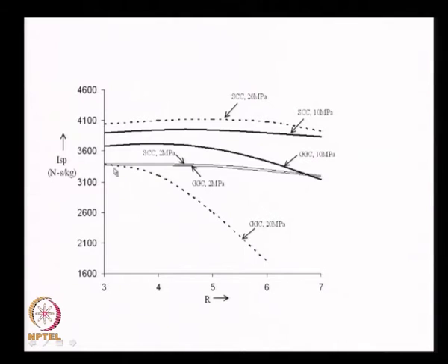All I am saying is, if I operate a gas generator cycle at a small value of pressure, this is the net value of specific impulse I get. If I operate the same engine on a stage combustion cycle at low pressure, I get a slightly better performance because I have not lost very much, as F is still small. I still find the gas generator cycle is lower than the stage combustion cycle, but the loss is small, because F might be something like 0.01. If I go to slightly higher pressure, what do I find?